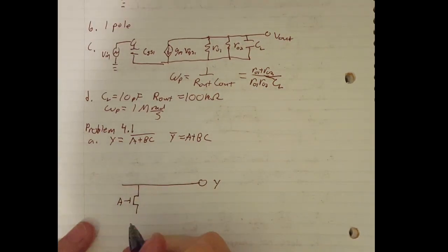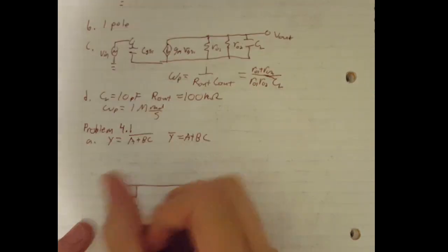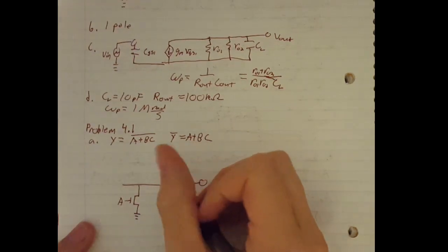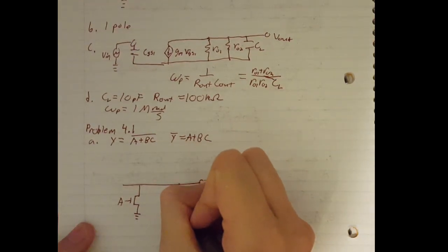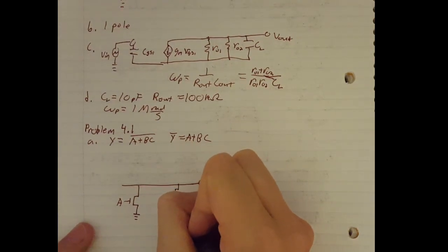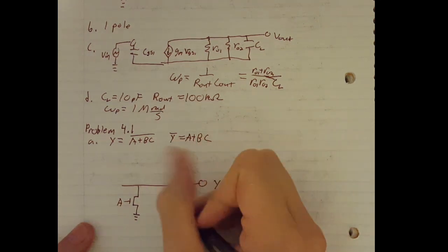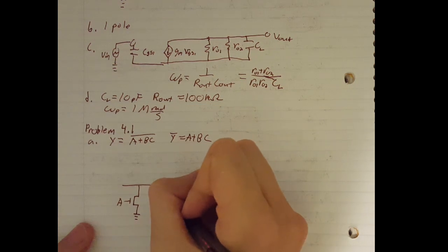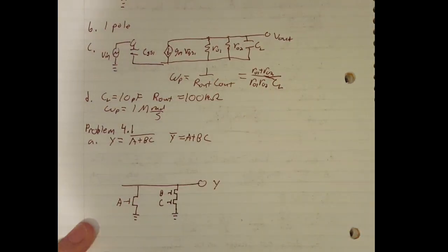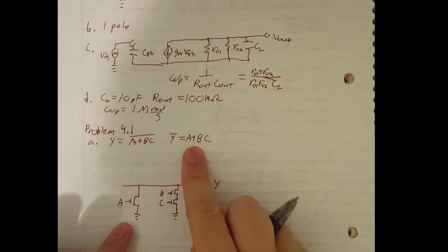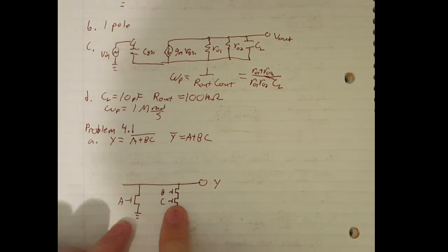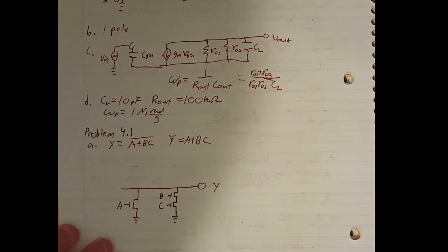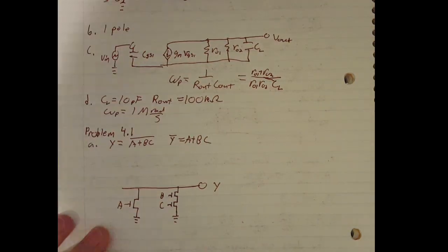And I'm going to use digital notation for these transistors because it's a digital circuit. You can use analog source if you want, as long as the grader knows what you're saying, you're fine. So I just did A, or B and C, and that's the pull down network. And so let's flip that into the pull up network.